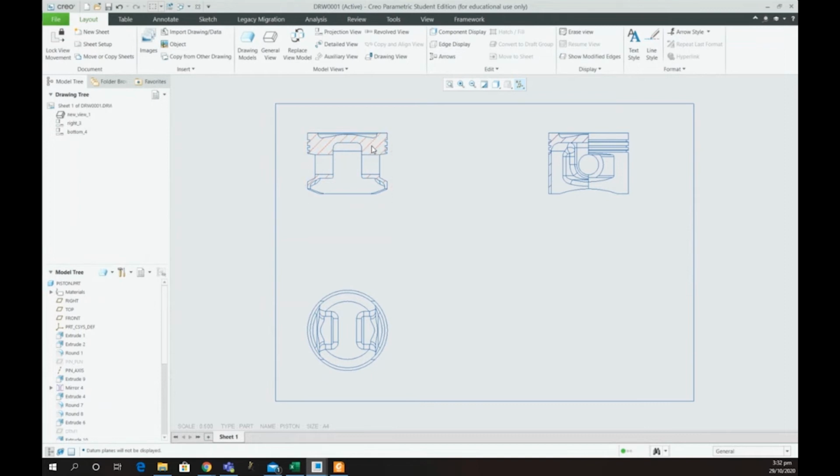We are going to create a fill over here, and we are going to change these hatch lines to smaller ones. But again, I'm just doing this to show you. Otherwise, you need to follow one convention all across your drawing. If you are doing fill for your hatching, just continue with the fill. If you are going for hatch lines, just go with the hatch lines and with a similar width. So to edit these, I'm not selecting the model this time, I'm selecting these hatch lines.